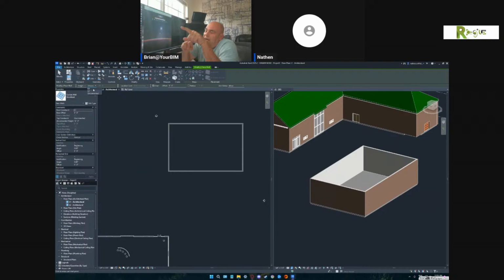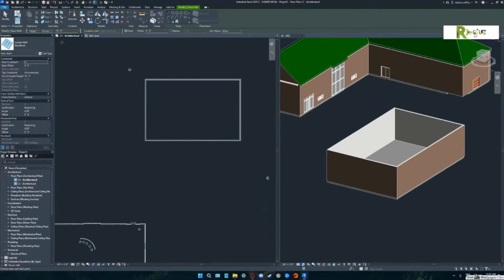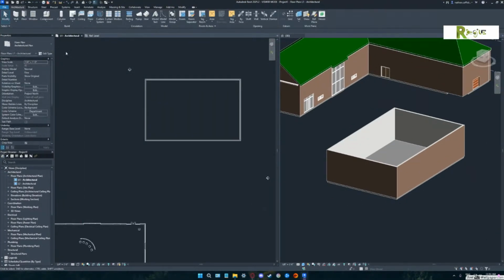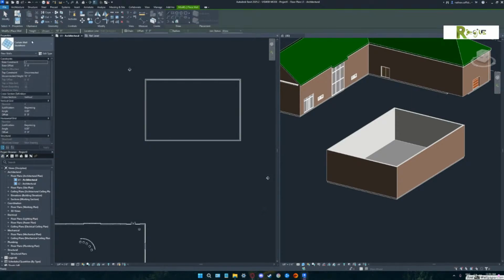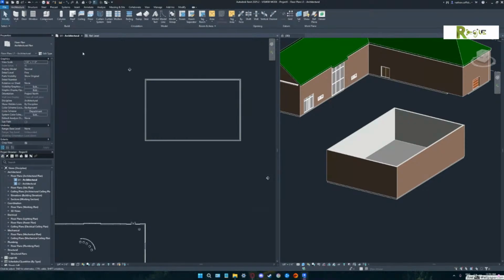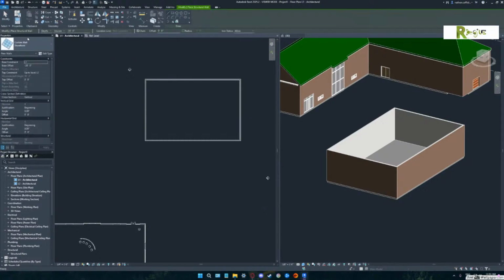You see how it says height? Yeah. All right, and here's something pretty interesting about that. If you were to draw a structural wall, you would find that it would not say height, but it would say depth. Hit escape. Go underneath the word wall, and you'll see structural wall below that. Wall structural. You notice how it doesn't say height anymore. It says depth. Yeah. Okay.